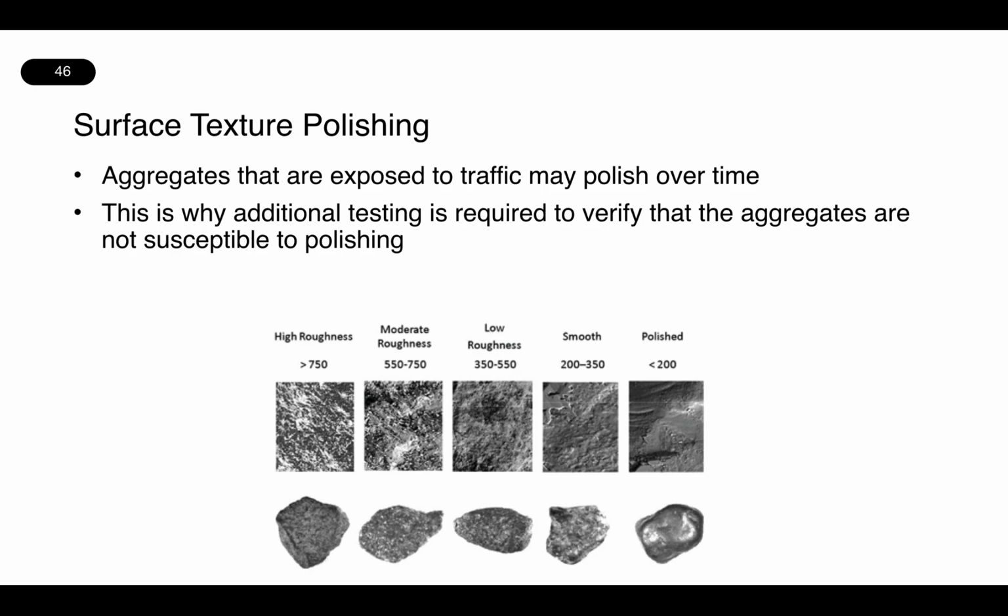And so for aggregate to be used in surface mixture, we require additional testing for polish resistance, and that's the reason for that. And that picture at the bottom shows you the differences between rough particles versus, there on the right, a particle that's very polished.